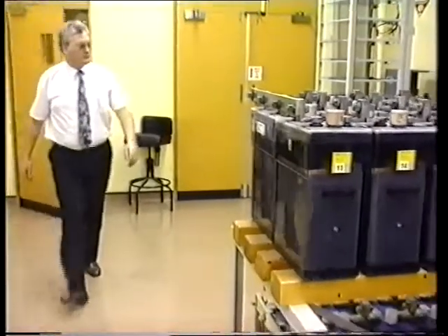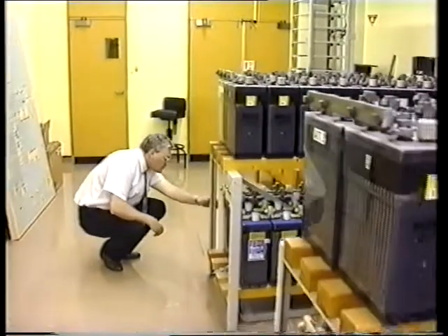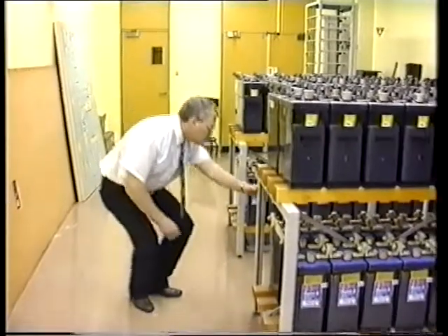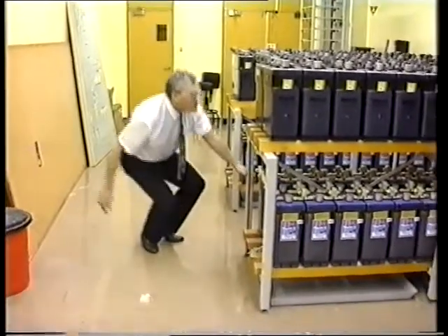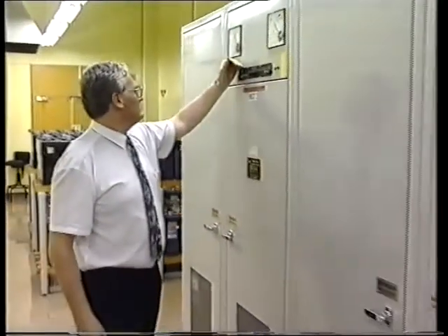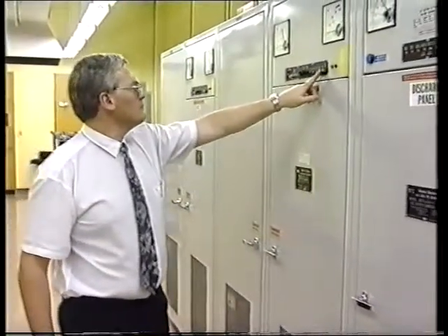Telephone switching equipment can also be powered using rectifiers, batteries, and a DC distribution cubicle, depending on the installation. This is arranged as an integrated power suite, commonly called IPS. Buck-boost power supply systems are not configured or operated in the same manner as an integrated power suite. This is an extremely important point to remember. Let us first look at the integrated power suite.